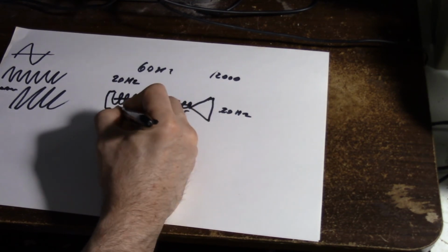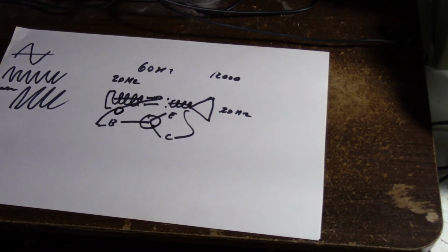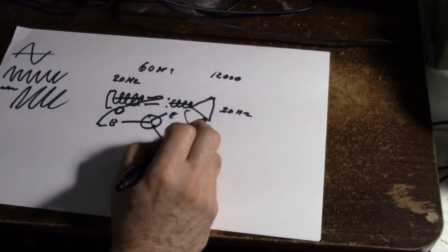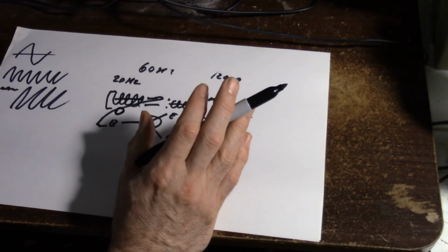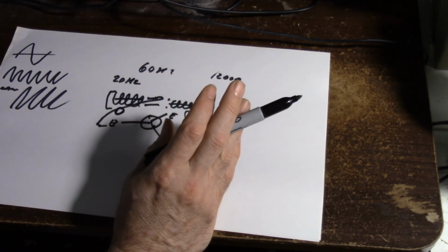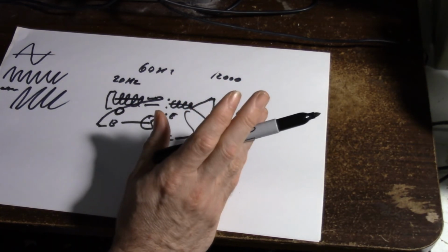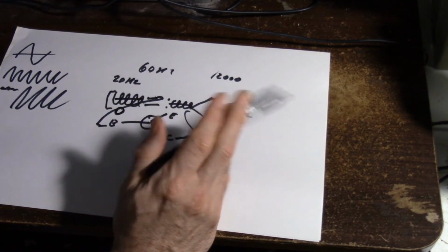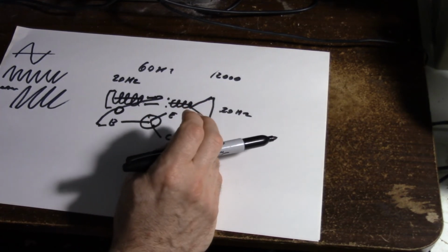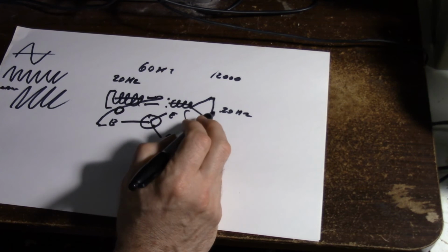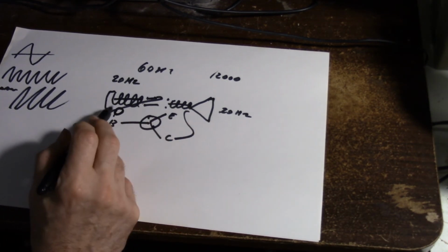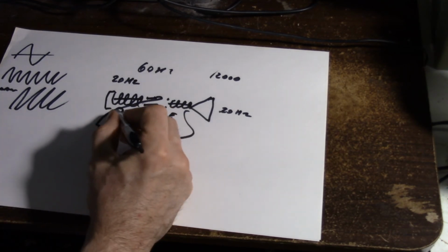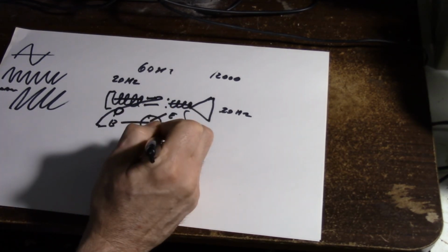And the gain control is usually on the input, because your output could be 100 watts, 200 watts, 300 watts. You would need a variable resistor that's that size. A 200 watt, 300 watt, 400 watt variable resistor would be huge. I don't think you could actually lift that. It would be very heavy. So we control this side. It's a much smaller voltage, and by controlling this, you can still control this.